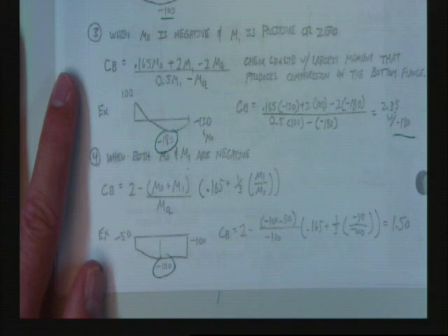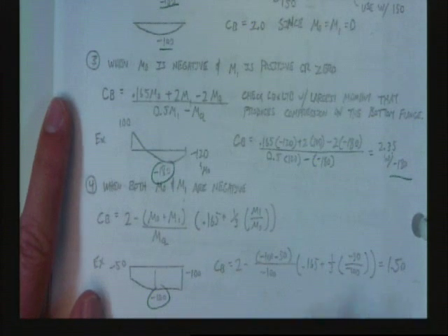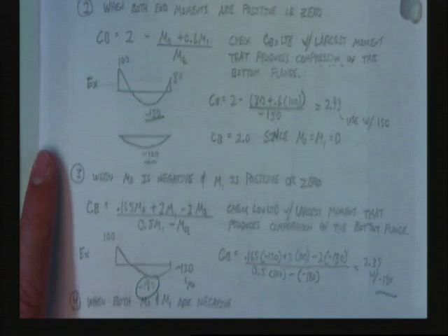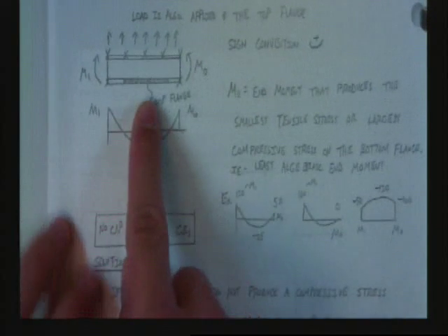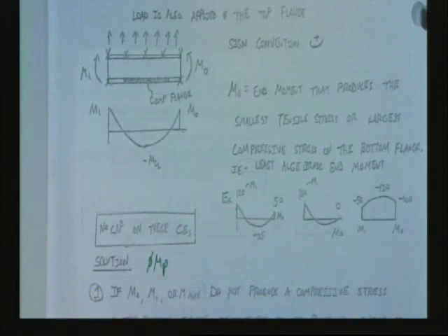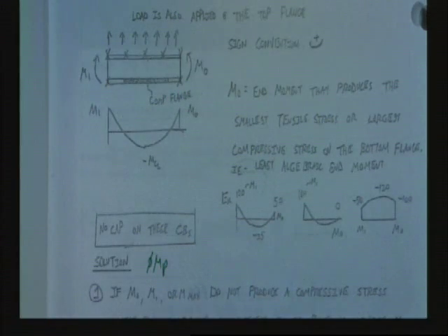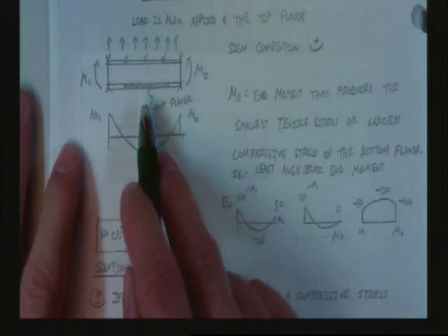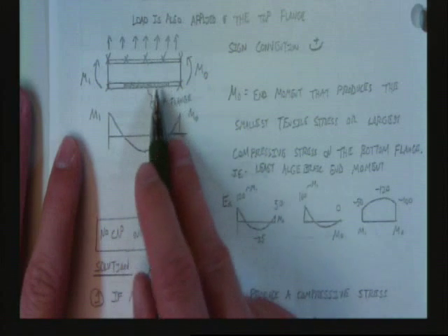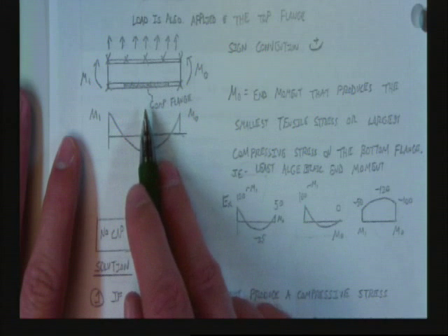Okay? Now, let's say you calculate these capacities and you find out you have an issue. It's not satisfactory. How can you improve your buckling capacity? What's that? Shorten the member. How can you do that? Shorten the ends. You could. How else could you do it? What's that? You cut it in the middle and make it like two short ones. It's not the best way to do it though. But you could cut it in the middle and make it two simply supported beams or whatever. I like where you're going though.